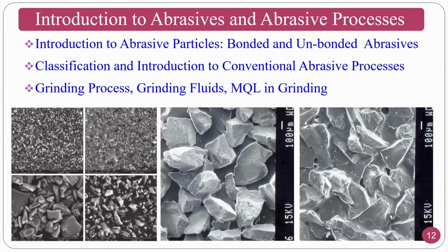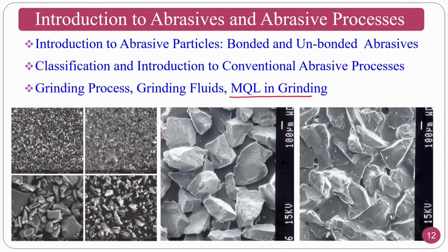At the same time, the good thing that we have studied is how to protect our staff. Even if you are an engineer in a company, for that purpose you have to find some sustainable solutions, wherein we have introduced you to grinding fluids which are biocompatible enough, which prevent environmental pollution to the maximum extent, and which will also reduce the problems faced by the operators. That means the system and surroundings will be maintained environmentally good, or you can say eco-friendly.